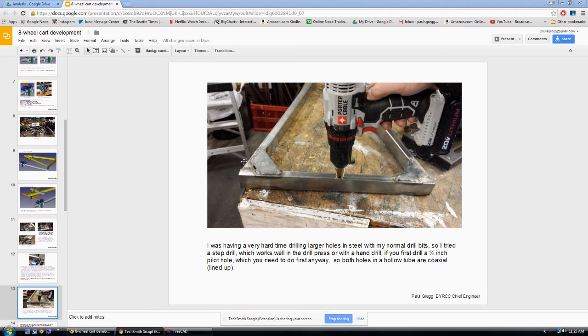The other thing is these gussets here on the end. I could have put these inside and put butt welds on the ends of them, but I think this ends up a lot better if you make them a little longer and then put a fillet weld around the end. You can also put a fillet weld on the backside, and there are 4 of these things, top and bottom. So this corner joint is very stiff and very strong.